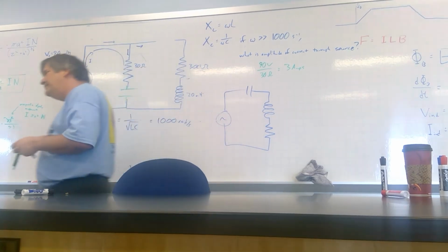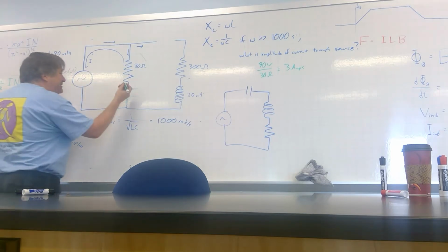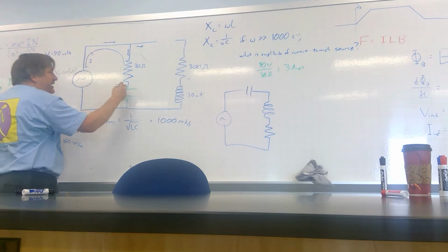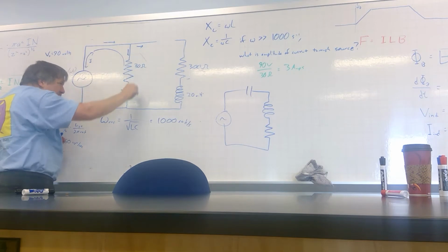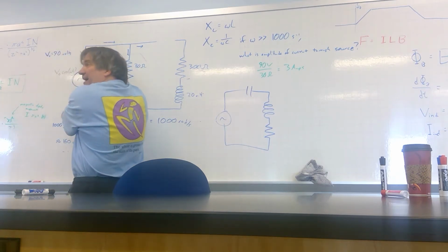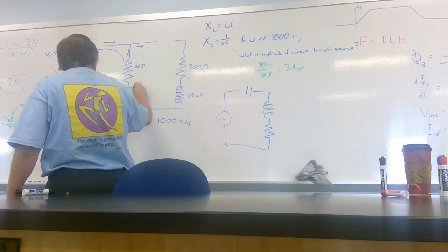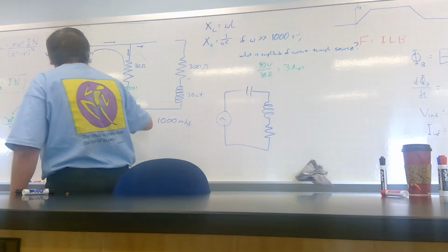So with slow frequencies, when current is flowing through the capacitor, is it just that the electron carriers will go across, but since there are so few of them, it doesn't even represent it? Yeah, well, it's not that there are few. It's not like the capacitor's not charged. If this is 90 volts, and I've got really low frequency, and I happen to be at the moment in the cycle when I've got my full 90 volt amplitude here, this capacitor will be strongly charged. It'll have as much charge as it needs to have that 90 volt drop across it.